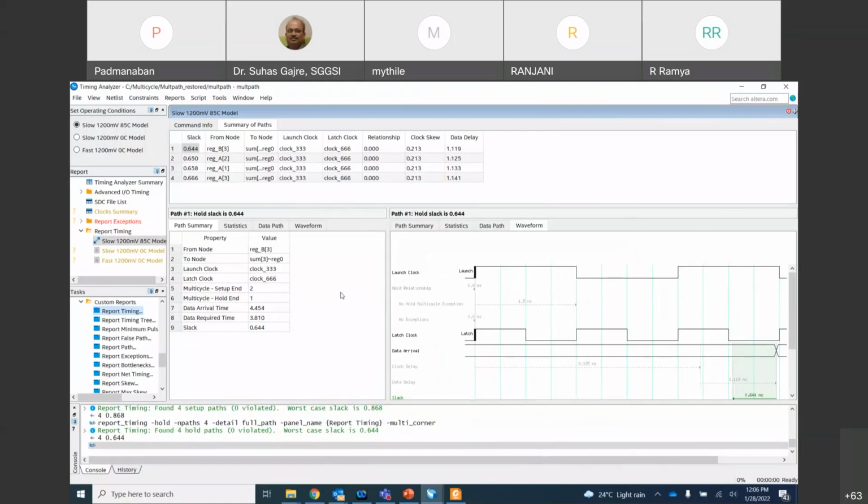What the understanding here is that the multi-cycle path constraints need to be applied for the design. Otherwise, you may require 2 clock periods, but you are asking the design to work in 1 clock period. Then the design is not properly constrained. So your design has to be properly constrained. Only then can we enter into the next step.